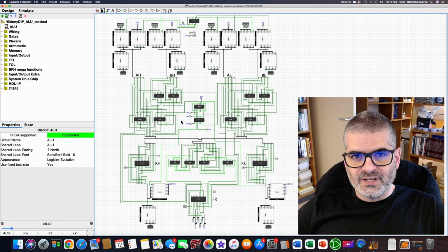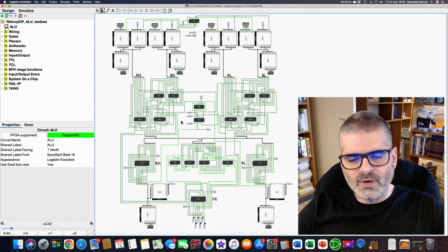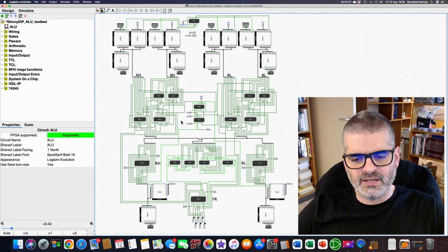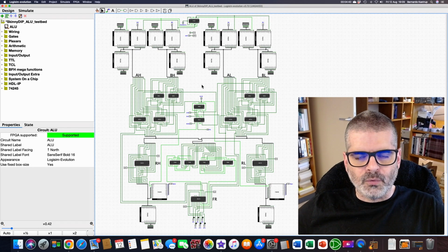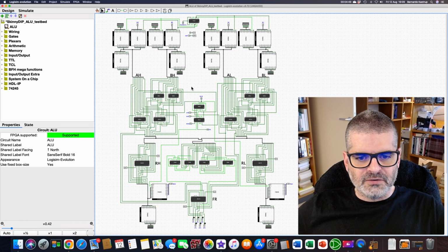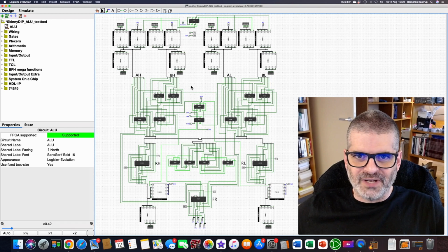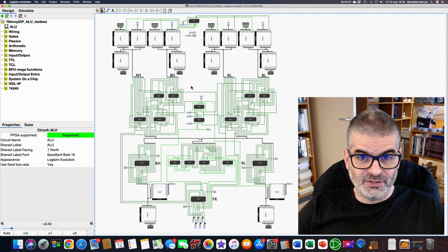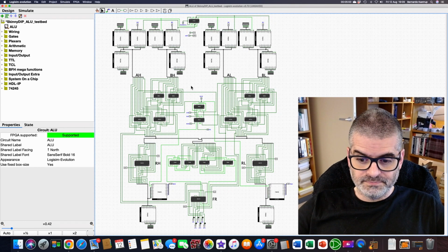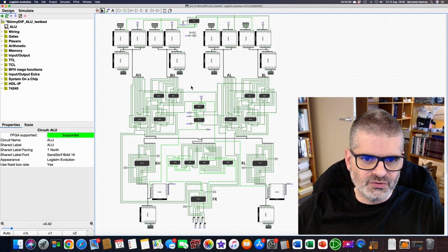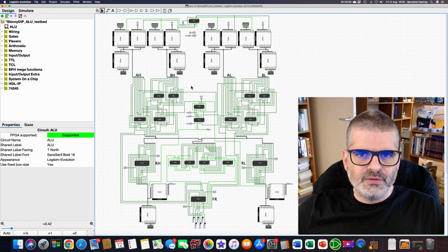So you want to make sure that you got your logic right first. So then you run a simulation at the level of individual gates without schematics. You just run that in a hardware description language. And then you move to something like this, board level schematics, to make sure that your board level netlist is correct. If you don't do a simulation at this level, you may find yourself having to build a breadboard prototype, which is today not feasible and not practical for most designs. I did it at Cerberus because I wanted to illustrate it, and because I didn't want to use non-public domain models of the complex chips I was using, like the 2 CPUs, the microcontroller, even my own 3 custom chips.